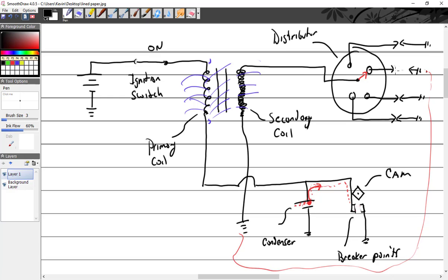But if you start packing all of these molecules of air into that space of a spark plug, which is only 0.018 of an inch, it starts to look to the electrical circuit like it's getting wider and wider of a gap. It takes more and more voltage to jump it. So as I put the air pressure on this little machine, I'm packing more air in between that little tiny gap, and it's in effect like taking the gap and spreading it out. And so it takes more voltage to jump that gap.